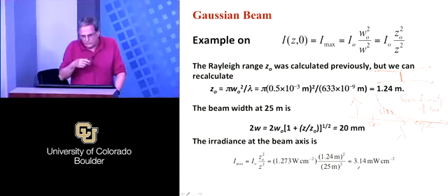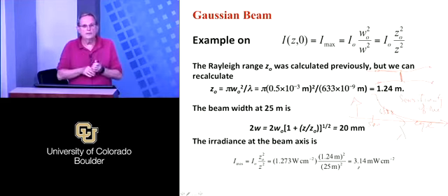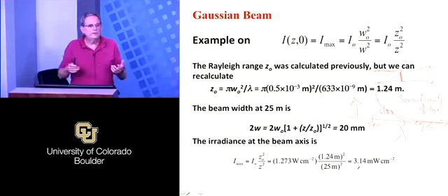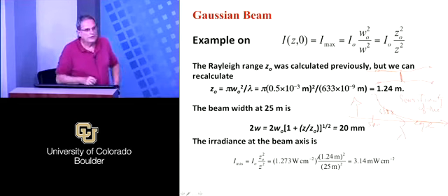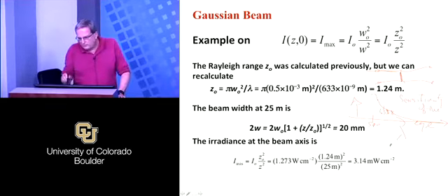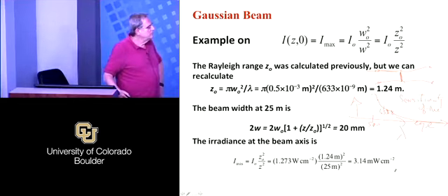Although there are arguments for going to 1310 for dispersion. But at 1550, you can have several milliwatts, and as long as it's expanding at a reasonable angle, there's no eye safety requirement whatsoever. Whereas in the red, this would still be dangerous, and this could be quite damaging in the green to the eye.